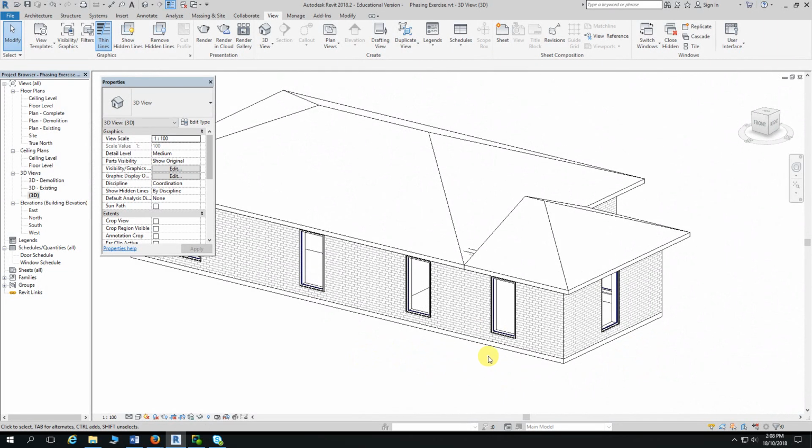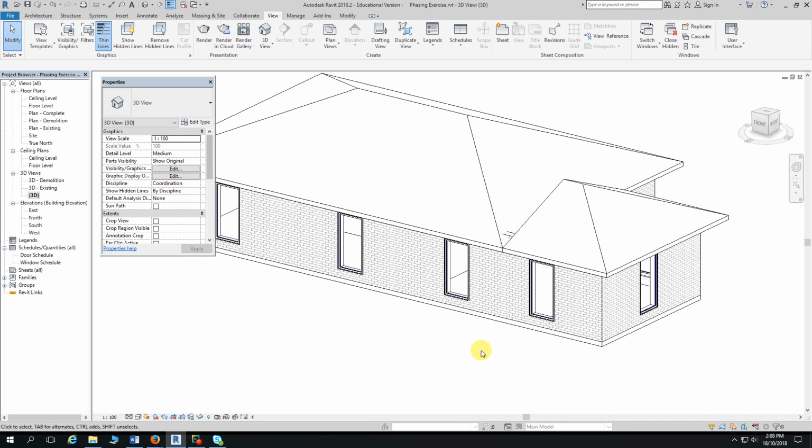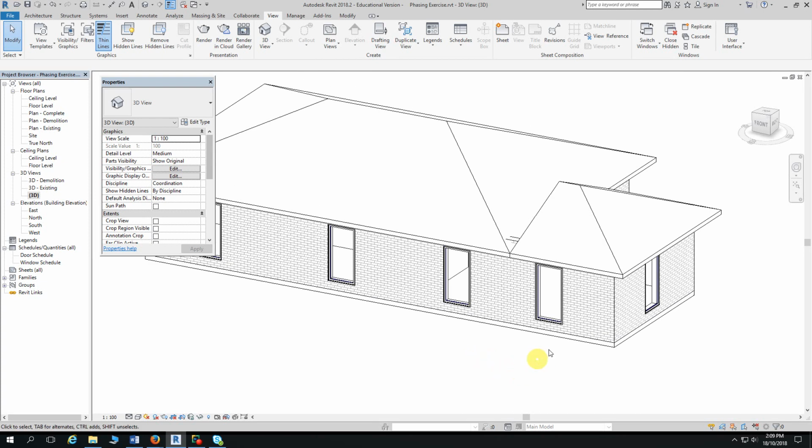Has anyone done any roof modification like this before? Essentially, the principle of creating sub-roofs is required when you are developing complex roofs. In this case it's required because we need to distinguish between the existing and the new construction. So the 2 roofs need to be separate. Now it is possible to join this roof with this roof, which is what we're about to do next.